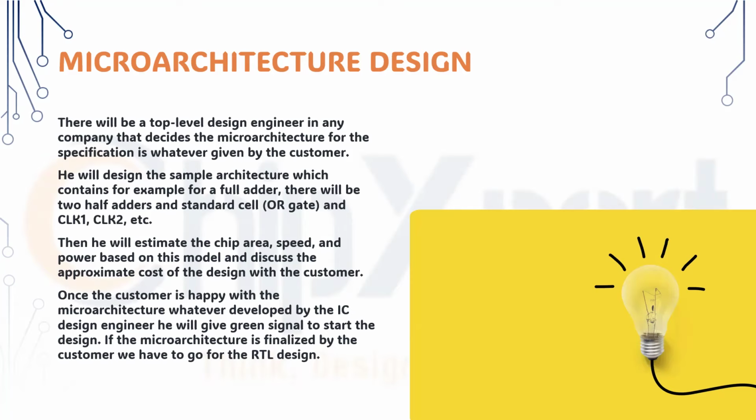Let's take a small design, like calculating a prime number. It will use around 20 to 25 basic gates, and it has to be designed in a Verilog format. First, it has to be defined as a combinational circuit. So first, we need to create it and check that the functionality is working correctly in a combinational circuit. Then we have to define it in a synthesized way.